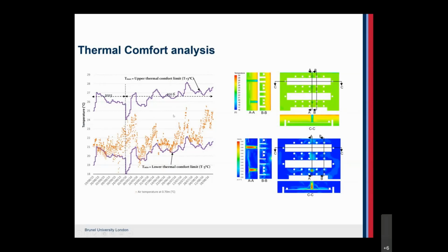The graph on the screen shows the results during weekdays from 8 in the morning until 9 in the evening for the seminar room for 2 summers. Temperature is the average of all the sensors that we have at 0.5 meters, seated people's height. We can see that the temperature did not exceed the upper thermal limit. In general, the low solar gains, because of the small area of the windows and the ground floor position of the room, allow the system to maintain comfortable conditions during the summer periods with full occupancy. For example, during the exams in mid-May and mid-August.